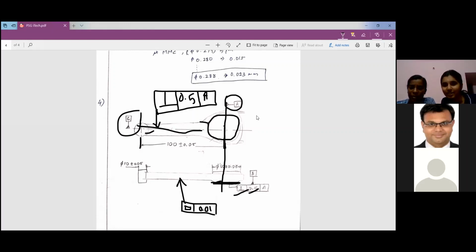No, sir. Here there won't be any, because both are cylinders, right? When it comes to circularity, you can mention it, but it will be very small, negligible. But again, the problem is this connecting rod has one end connected to the piston pin and the other connected to the crankshaft. So it has both reciprocation and rotary motion.